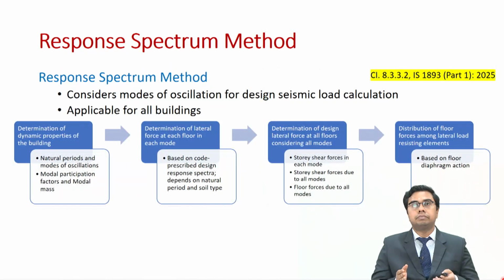Moving to response spectrum method, we were considering different modes of oscillations for the design seismic load calculation, and therefore it was applicable to all buildings. In this method, the first step is to determine dynamic properties of the building, which include natural periods and corresponding modes of oscillations. We also found out modal participation factors and modal masses corresponding to different modes.